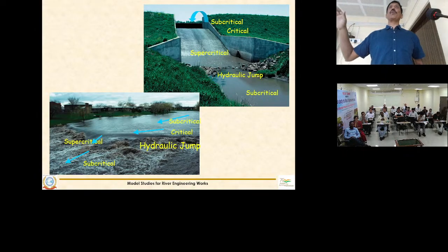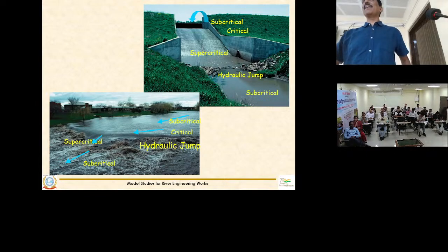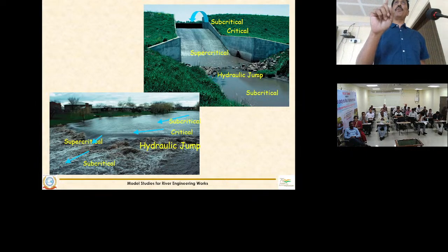If you are considering a reservoir, it is subcritical. When it comes to the weir, at a certain point there is a critical depth. At that depth we try to have the rating curve, because there is only one depth. So at a measuring structure, we always have to measure the critical depth, because that will give only one depth; it is not based on the regime.